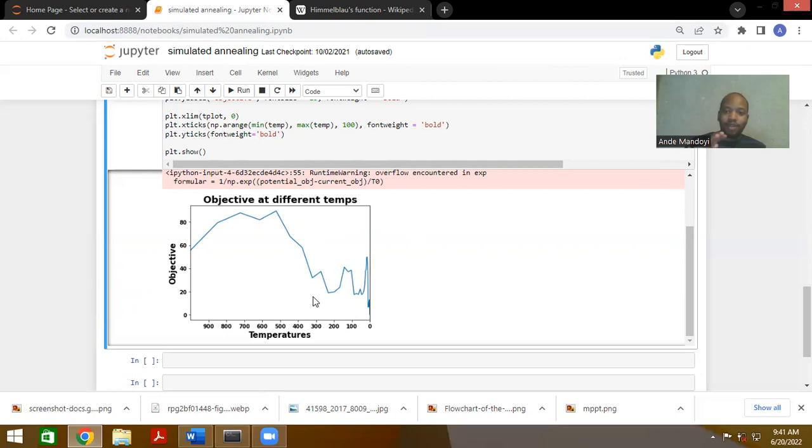I know that this is a continuous problem, and what we're trying to solve is more of a combinatorial problem with this MPPT. But I'll show you how that is done on MATLAB, and we'll actually just implement it, run the code, use it within our buck converter that we linearized and we controlled, and introduce a couple of panels in there. I am not going to do the cell balancing and other battery circuits. I just bought those off the shelf. What I am going to do is the MPPT.